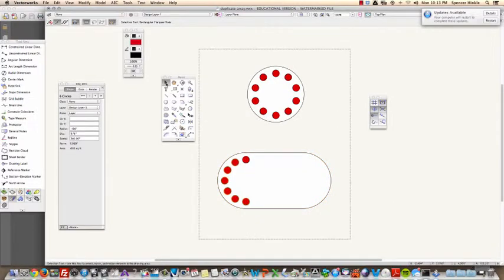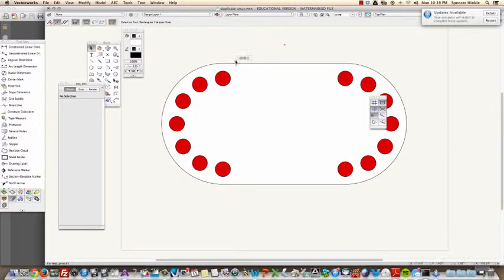Now let's do a mirror duplicate. And I'm just going to select those circles, and I'm going to go to the mirror tool, make sure that I have mirror duplicate on, and I'm going to come to the midpoint, draw my line, and there we are. All right, let's do the linear array and then the rectangular array, and we'll be done with this.